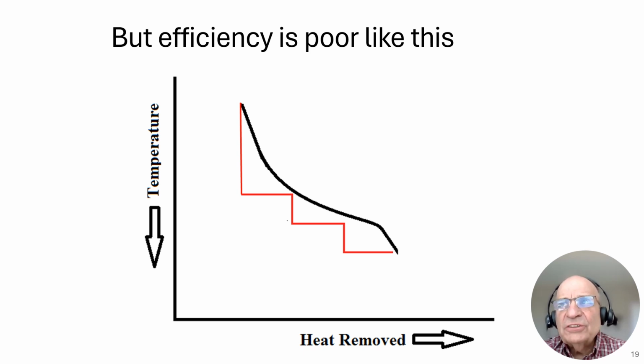What I showed you earlier was just a three-level cascade system to get down to minus 180 degrees Fahrenheit. If we were trying to make LNG with that, we'd need to extract LNG at each of the processes using the propane loop and use the propane loop to cool the ethylene loop. At the ethylene loop, we cool the natural gas and we cool the methane that has to go down to the lowest temperature, minus 180. And at the lowest temperature, minus 180, we would cool only the LNG that's already been chilled by the propane and the ethylene process.